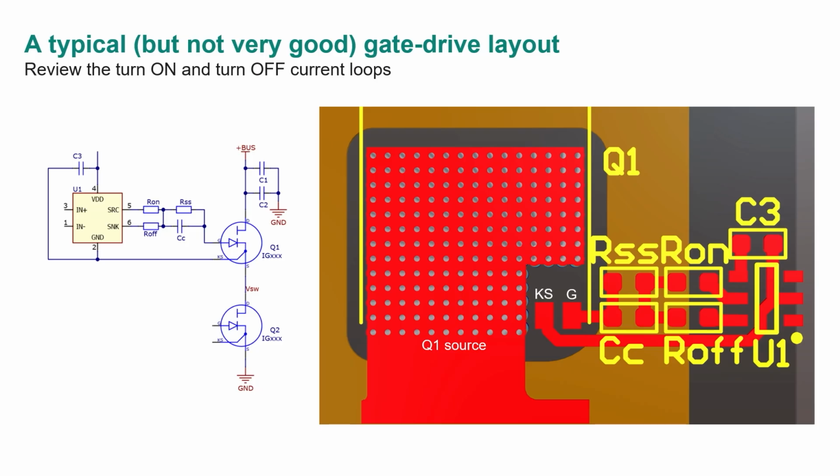So now we talked about the design of the gate drive circuit and how to power it. The next thing is making sure that the circuit layout on the board is workable, that it doesn't create additional problems. Let's take a look at a traditional layout of a gate drive circuit that I see all the time. First-time users with GaN will often do this.